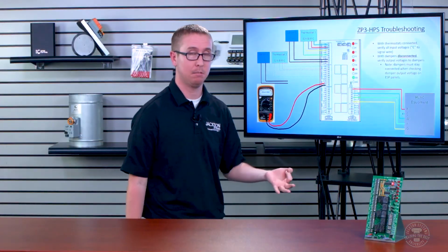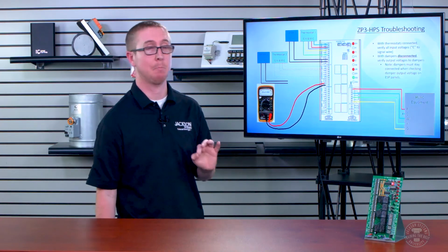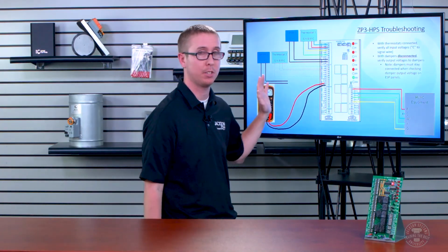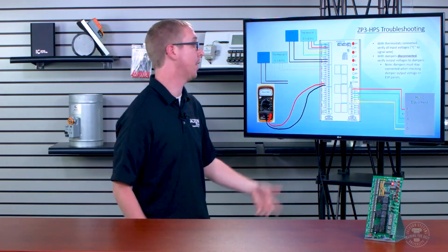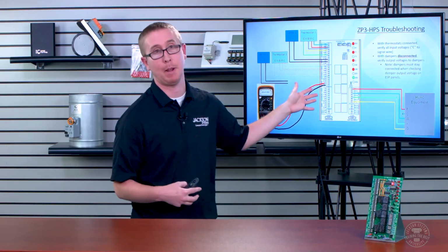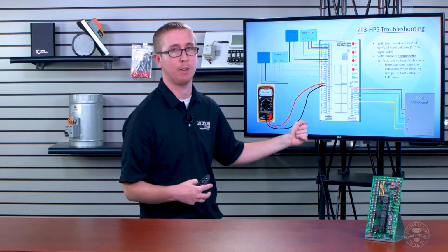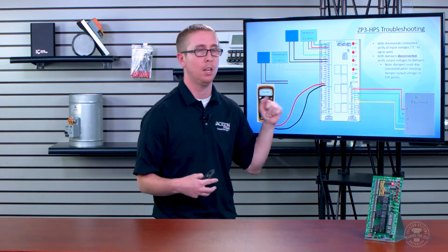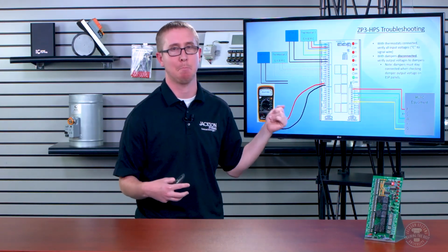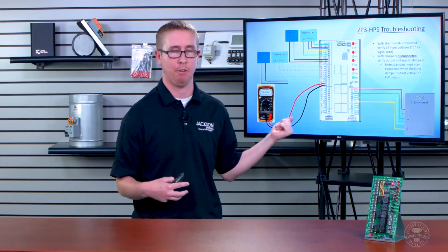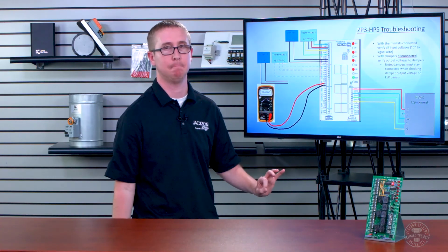And then oppositely, ESP panels are the exact opposite. So if you have an ESP panel, the wires from the dampers must stay connected in order to read an accurate voltage reading. The reasoning for that, just for some background, is that standard panels use relays to shoot out voltage out of these outputs, so you have to remove the wires to get a good reading. ESP panels use triacs for those damper outputs. Triacs depend on a load before they read accurate voltage. So you need to leave those dampers connected on an ESP panel only.